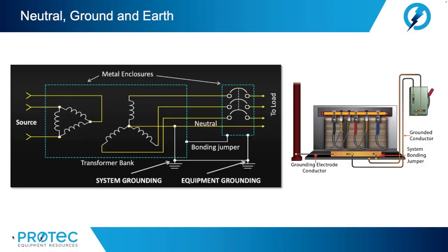Let's start with the definition of neutral. Neutral is a circuit conductor that normally carries current back to the source. The neutral is usually connected to earth or ground at the main electrical panel, street drop, or meter, and also at the final step-down transformer of the supply. That is for simple single-panel installations. For multiple panels, the situation is more complex.